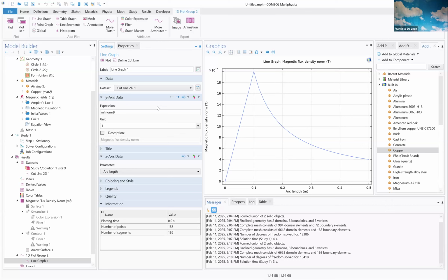Why would it be linearly increased? Because we have a uniform current density distribution. If you increase the diameter, it will increase by r squared, so it should not be perfectly linear. You will see when you do the integral that in cylindrical coordinates you have an r, so that drops your r squared to only r.